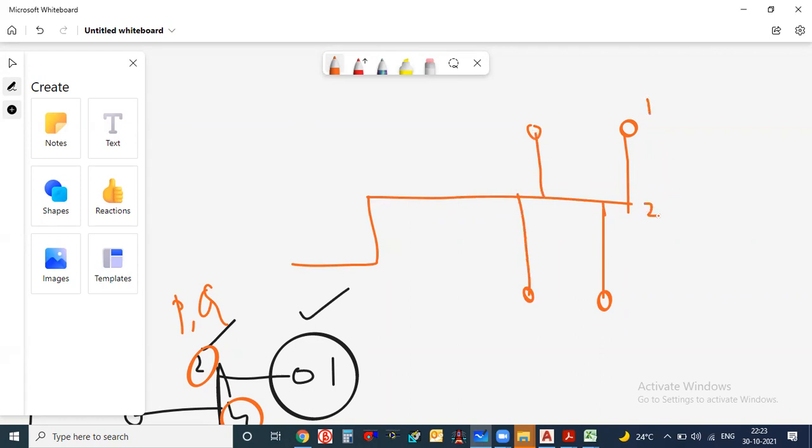Like I will give 1, 2, 3, 4, 5, 6, 7, 8. Now, if I'm doing the hydraulic calculation like this, it will be very helpful. So I can easily get the pressure at each and every pipe section. Like I can get the pressure at this point, at this point. So at each and every point I can get the pressure easily.